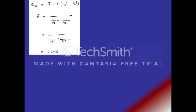Now we will proceed to calculate the heat transfer between the shield and plate 2. That is epsilon bar into sigma into A into (T3 power 4 minus T2 power 4). Here we calculate epsilon bar between the shield and plate 2.